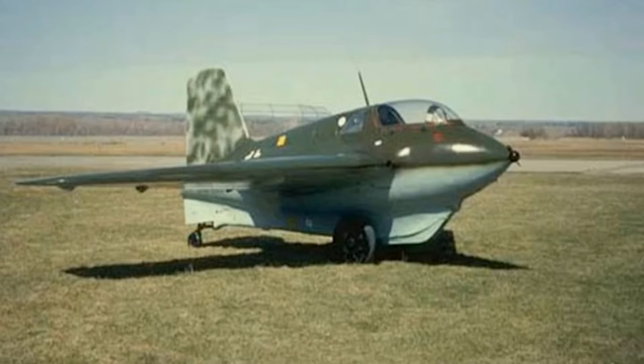It would be ideal to replace it with some ground-based equipment which detached on takeoff, as with this Messerschmitt Comet. But while it's possible to achieve manoeuvring and support for the aircraft with ground-based equipment, no satisfactory alternative exists for absorbing the kinetic energy of landing and providing a means of controlling deceleration. For this reason, a vast amount of research has gone into the design of undercarriage units in order to reduce their weight and their stowed volume when retracted.